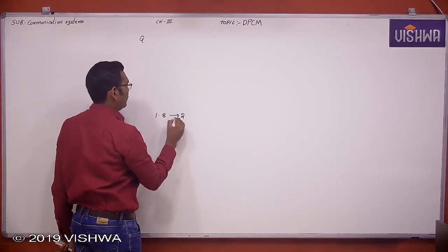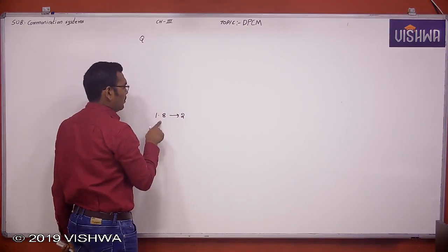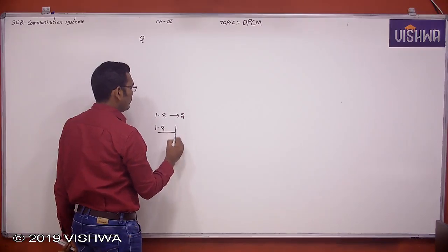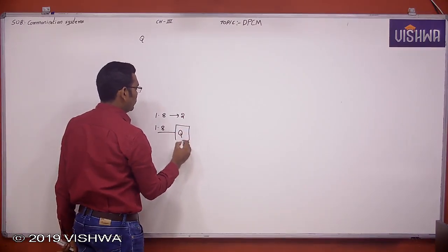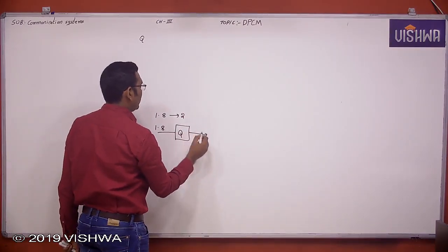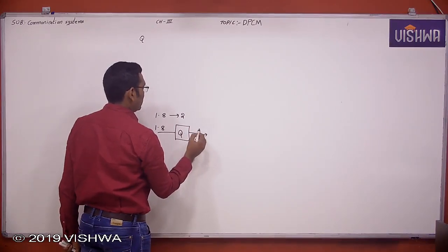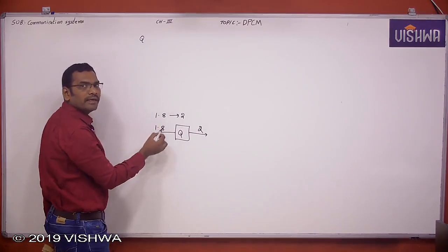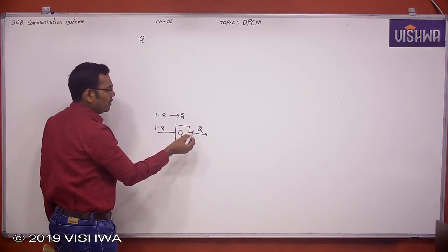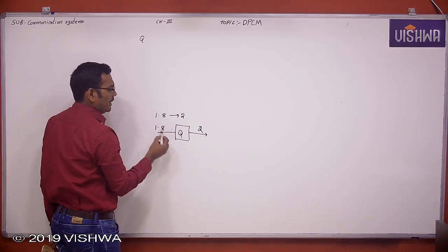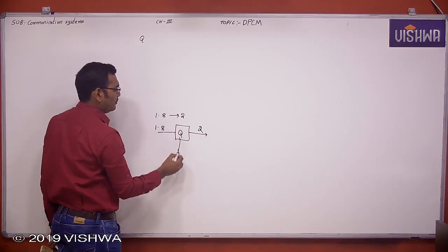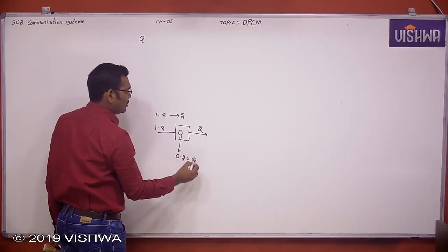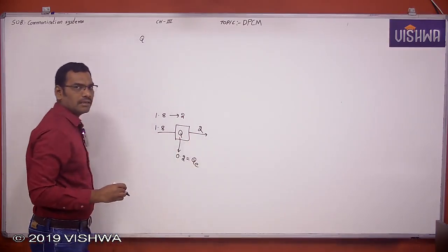The sample value goes through the quantizer, and at the quantizer output you get 2. This means 1.8 is rounded off to 2, which introduces an error of 0.2. That error is called the quantization error. Is it right or not?